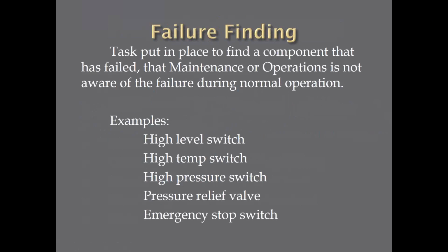What about failure finding task? It says here, a failure finding task is a task put in place to find a component that has failed, but maintenance or operations are not aware of the failure during normal operation. So some examples of these: a high level switch in a tank. When the liquid gets up to the high level switch, it does some action. It shuts a pump off or closes a valve. How do we know that that switch is going to work when we need it to work? Well, the best way is we have to test it.